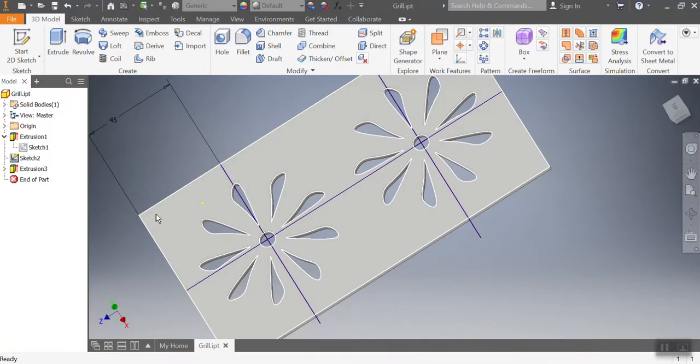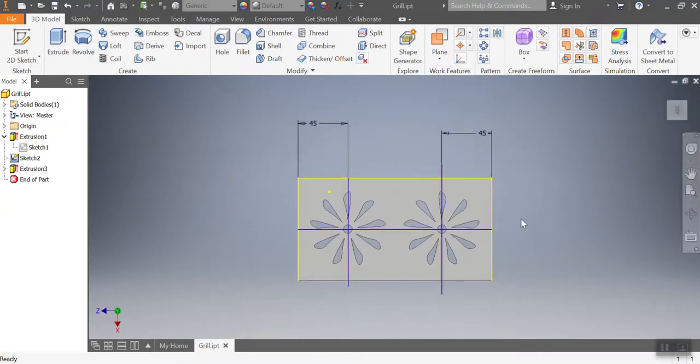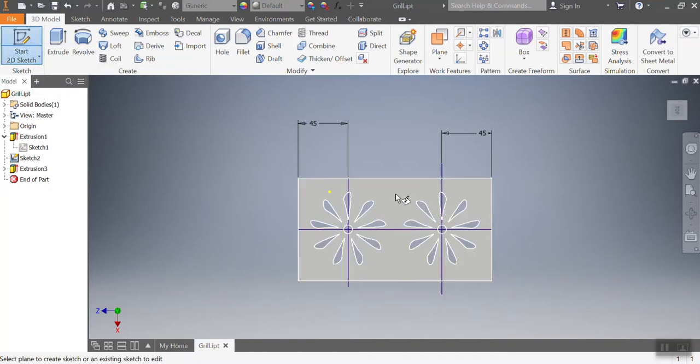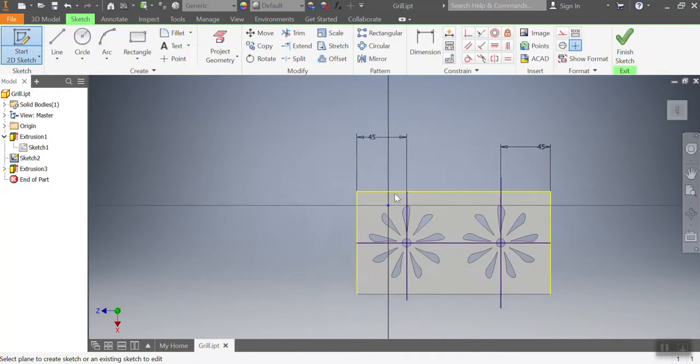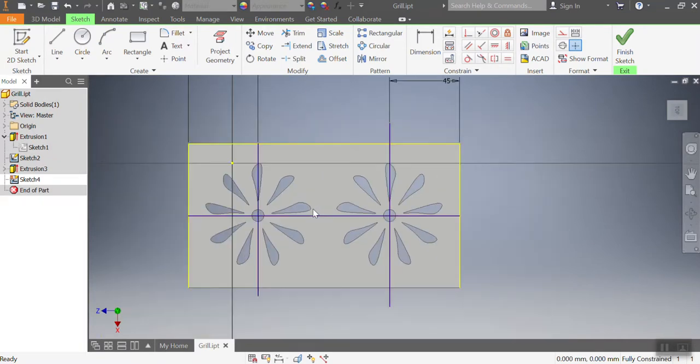All right, we're just about done. What we need to do now is put some screw holes here in the corners. So to do that, let's have a look, click on the top. There we go. And we're going to, again, start a new sketch. Choose the front surface. There we go. I can zoom out and zoom back in just to have a better look. Now what we need to do is do some grid lines. So with a line and just down.